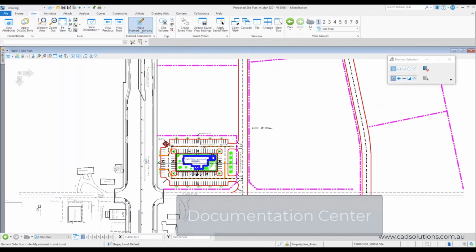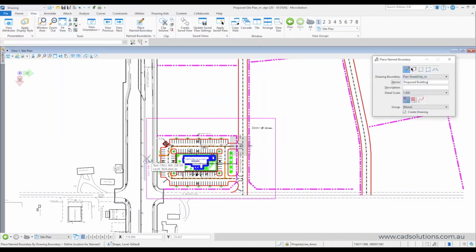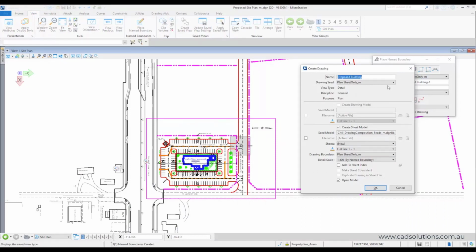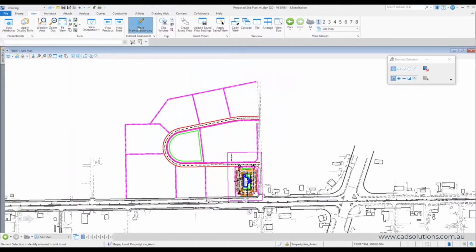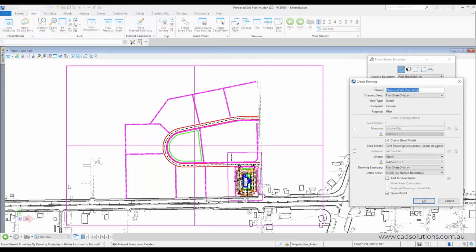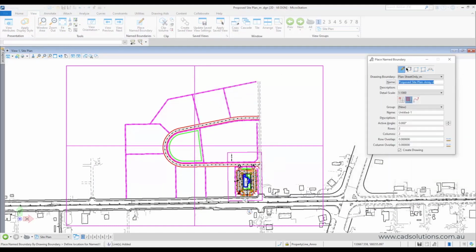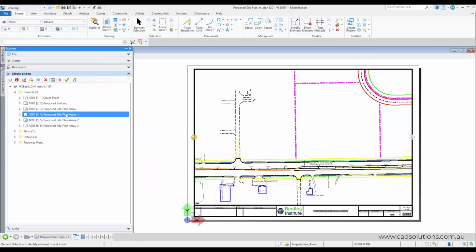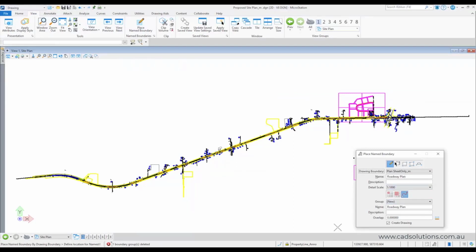Traditionally, the laying out of drawings onto sheets is a time-consuming and error-prone process that is done differently by everyone on a team and can cause inconsistencies and delays in getting projects delivered. To overcome this, as part of the production solution for accelerated sheet creation and layout, the Drawing Boundary feature is provided to allow you to quickly and easily define the location of a drawing on a sheet. A drawing boundary is a predefined area on a sheet model which may contain a drawing.